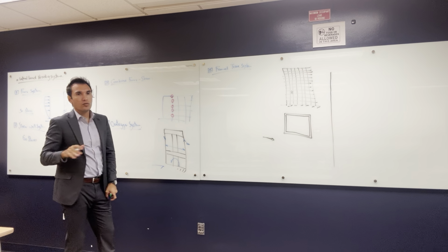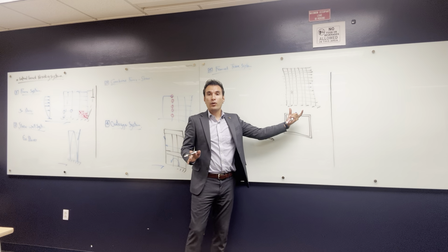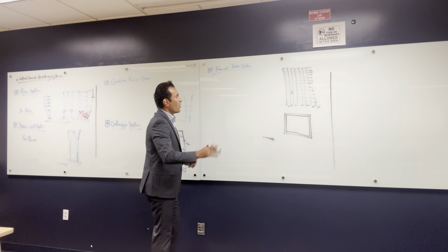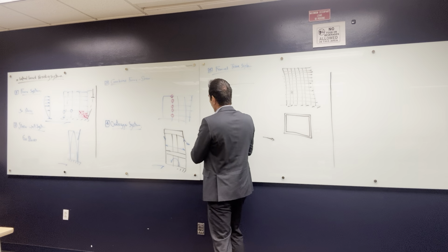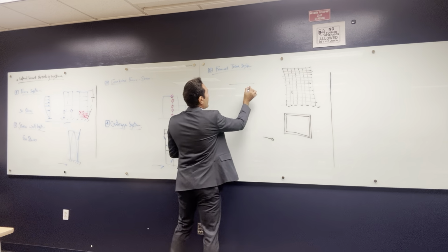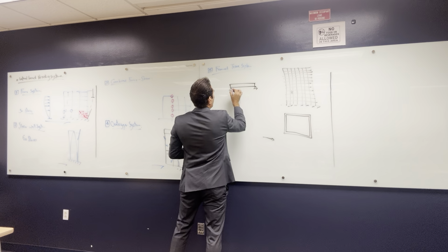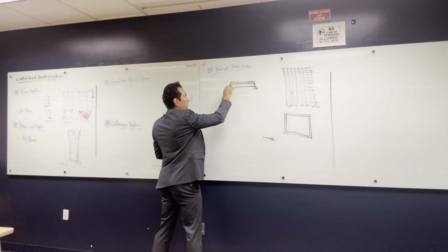But the thing is, I told you about the phenomenon that shows up here. When we use a perforated shear wall, it's called a shear lag, which decreases the performance of the building. Okay, so do you guys remember, if I have a beam like this, and this beam has a specific push like that, and definitely it's gonna bend that way.